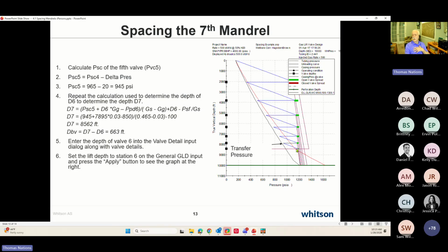If we have no packer in the well, just open-ended tubing, then the tubing tail actually acts as our bottom gas lift injection point. But we would go ahead and space valves at some even spacing number here, some bracket below this point here. Typically we'd call these unloading valves and then operating valves down here in this area.